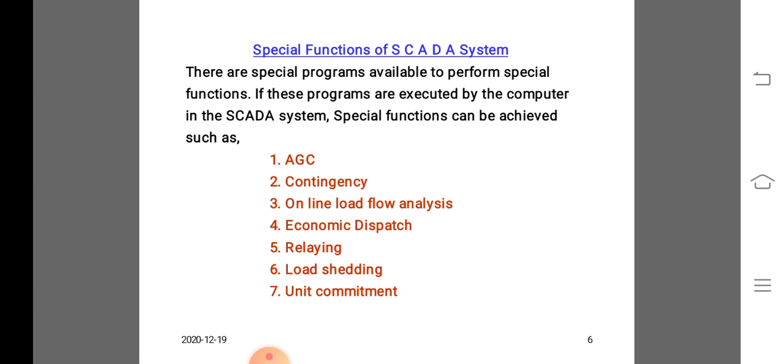It has some control functions, monitoring functions, and some other functions. First, we have to see the control function: control and monitoring of switch devices, tapped transformers, auxiliary devices, etc. This includes bay and station-wide interlocking, automatic functions such as load shedding, power restoration and high-speed bus power transfer, then time synchronization by radio and satellite clock signal.